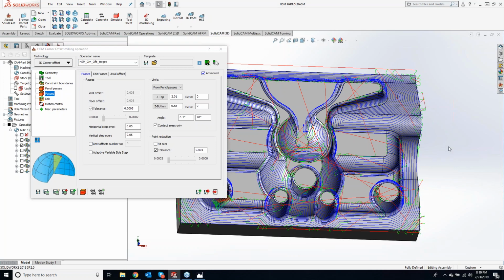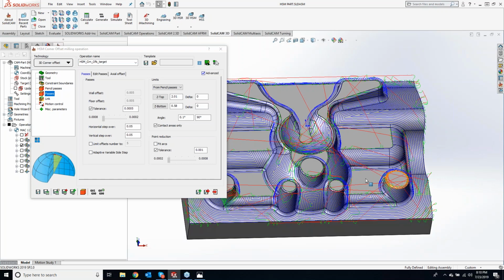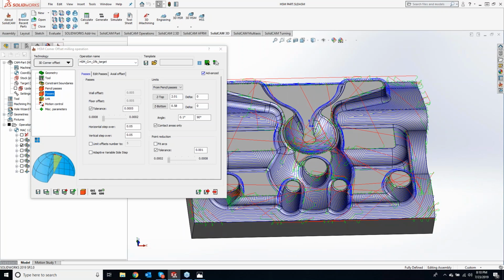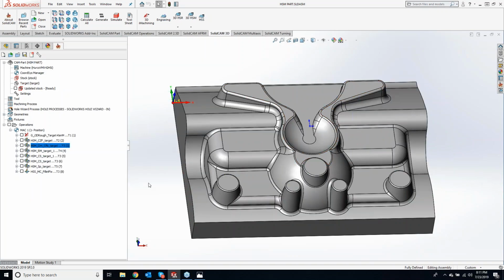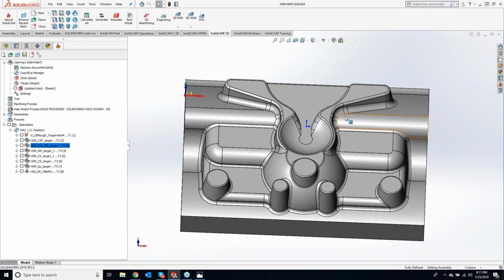But like I was saying, we would not want to tackle this entire part using HSS, because we'd have to break this up into many different regions. So like I said, HSM works very well to throw a blanket over the entire thing. Now, HSS is specifically designed, and hopefully I'm not repeating myself here, to work on just single surfaces or a couple of surfaces together.